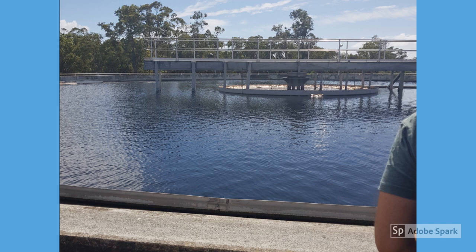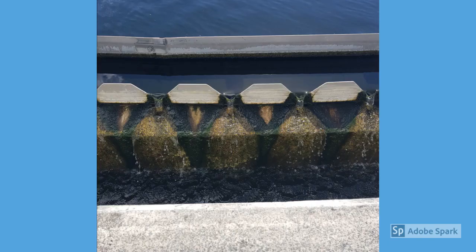The water entering the clarifiers is pumped into a central ring, as can be seen in the center of the photo, and overflows into the main body of the clarifier. From there, the sediment begins to settle immediately as the water travels outwards. A weir that runs around the perimeter of the clarifiers ensures an adequate retention time to allow particles, sludge, and sediment to settle out. The water running over the weirs of the two tanks is clear, clarified water that is now ready for the final phase of treatment.